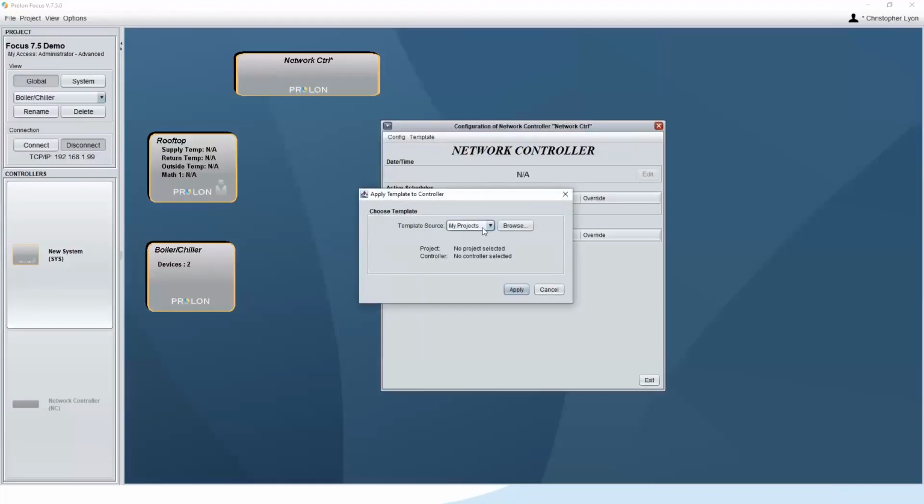Okay, if you've been to the trainings, you've heard me talk about snapshots and the importance of taking your snapshots, especially before final delivery, before you turn stuff over to the end user. Get that snapshot to prove it as a restore point. After you've proven everything, you've commissioned it, you know it's working, that way you have a restore point if you need to reset things. So you have that snapshot.